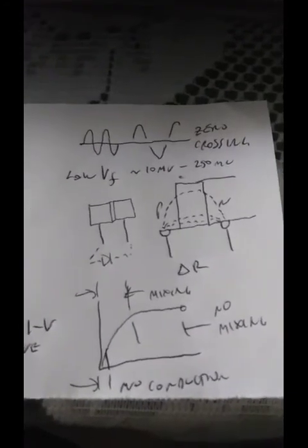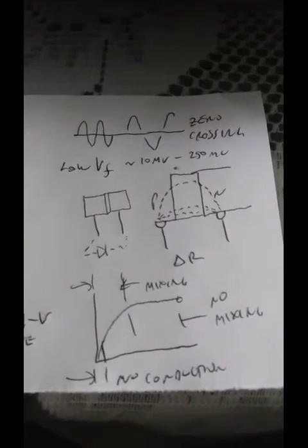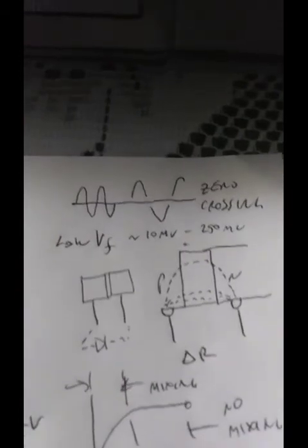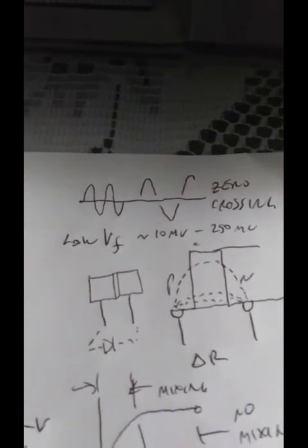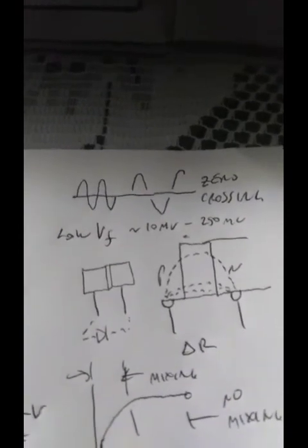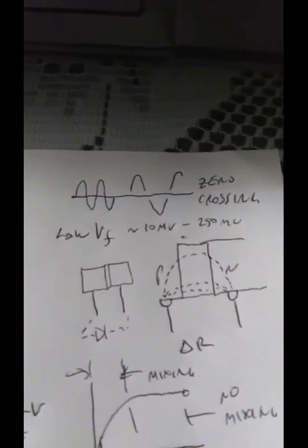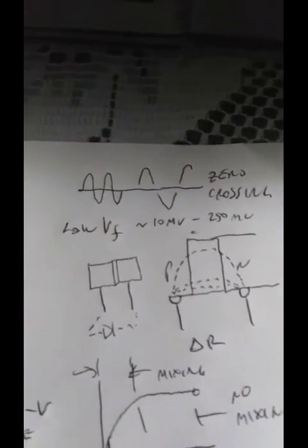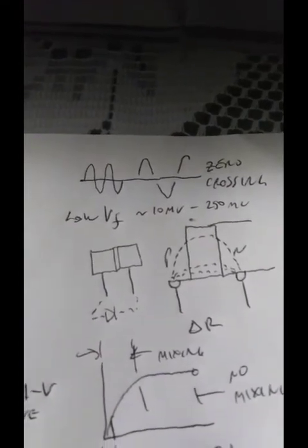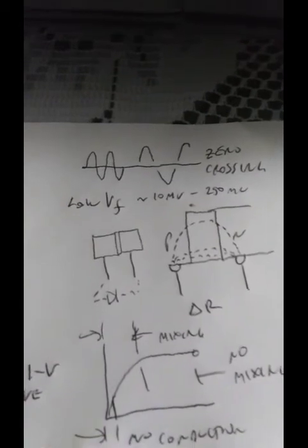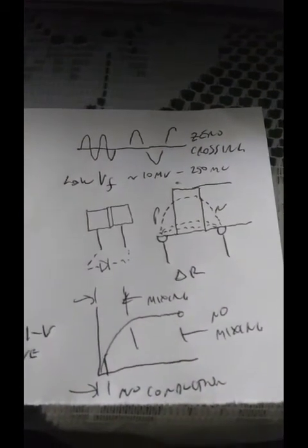At very low currents, that drop might be 25 millivolts. So that means that almost all of the modulation envelope can be devoted to mixing. And it also means that if we know where the noise floor is in the modulation signal, we might also choose a rectifier that can clip that out. So there's an advantage to not having it too low.